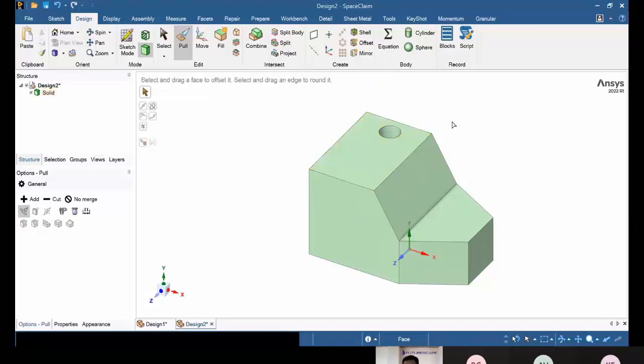In another CAD software, if I want to move this very cylindrical hole from one place to another, it will be quite difficult, right? Over here, we do not need to create a plane or sketch again or worry about the structure tree, because over here, everything is parametric. We do not have a predefined history over here, although if we want, we can create one through blocks.